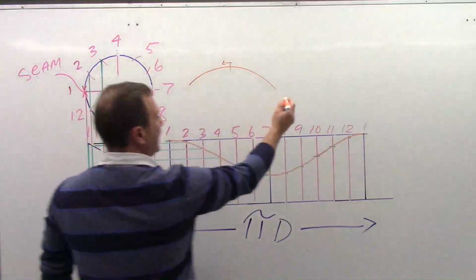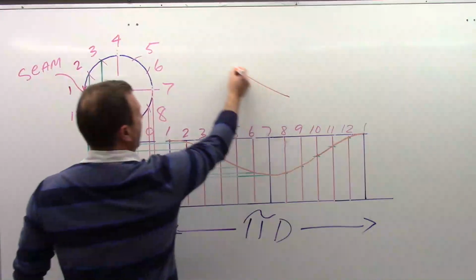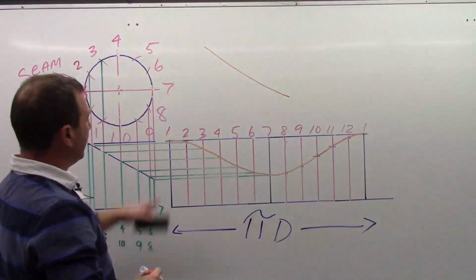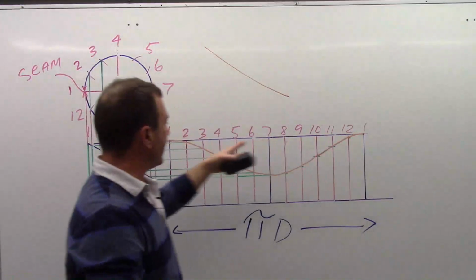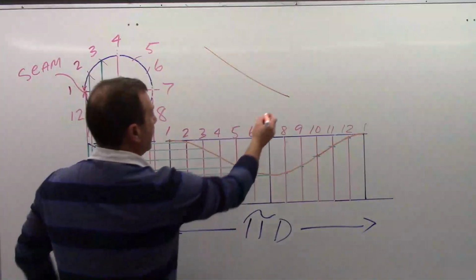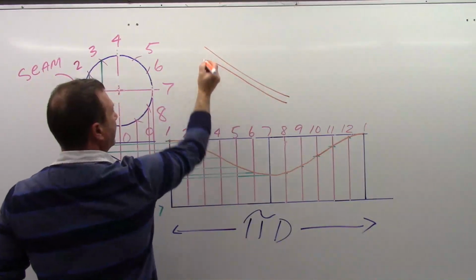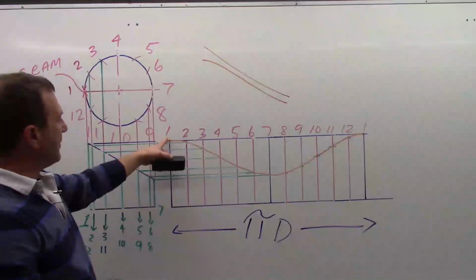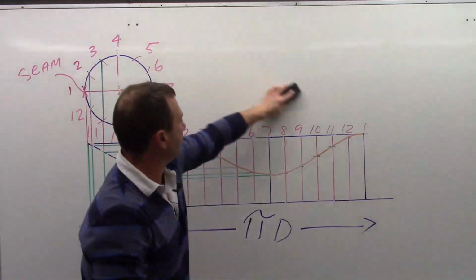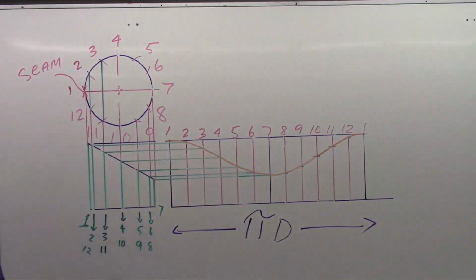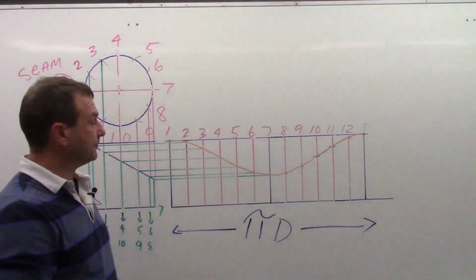So what we don't want to see is a line that sort of comes up and it's still heading up. Okay, we don't want to end our pattern like that. We always want to recognize what's happening on the other side. And in this case, it's going to go down, so that means our line is going to come up and crest off before it ends. So at the end point here, we want to keep that in mind. So now we have our pattern. We can take that to the shop, roll it up, and have our part.